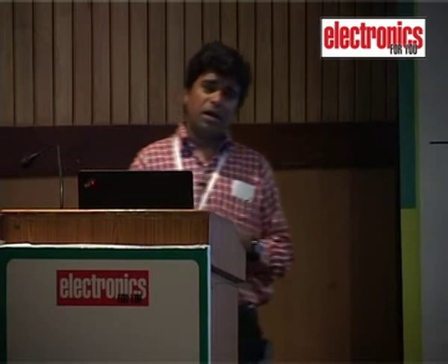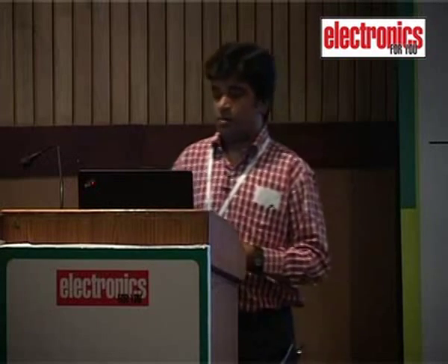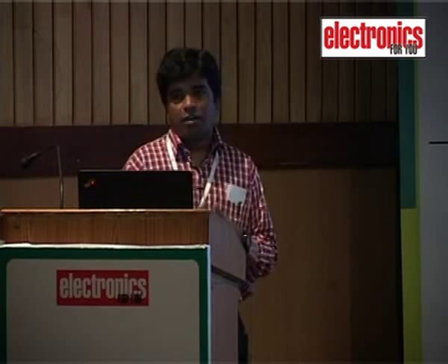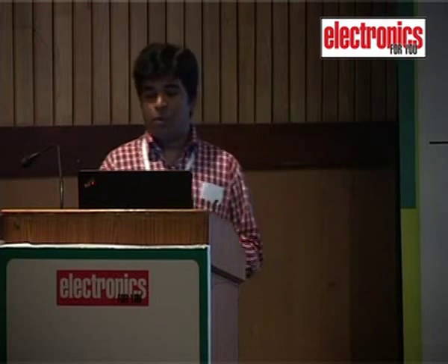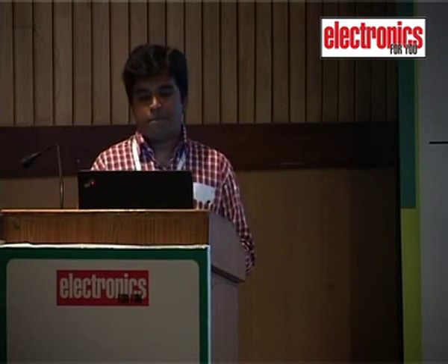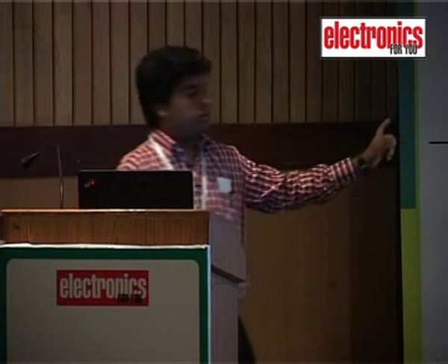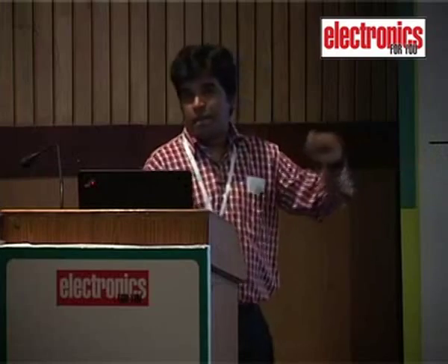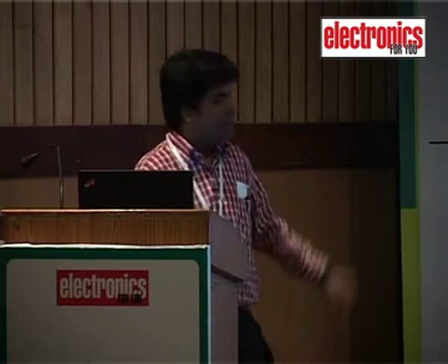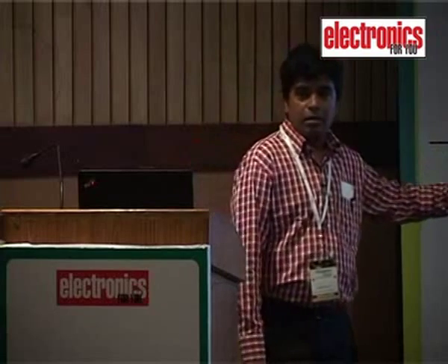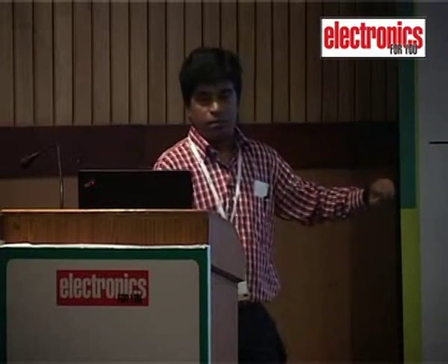When we deal with red, green, and blue as basic components of a color for any pixel representation, red or R can be expressed in 8 levels, green is expressed in 8 levels again, and blue is expressed in 4 levels. So essentially that gives a distribution of 256 levels for a whole pixel of entire color comprising RGB, where R and G are in 8 levels and B is in 4 levels.